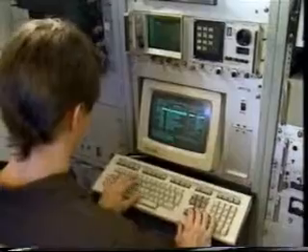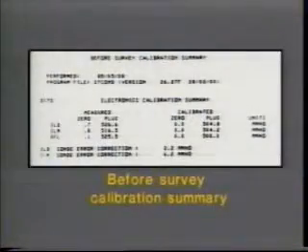Since this procedure is somewhat cumbersome at the well site, calibration resistors in the tool reproduce the values obtained during this periodic check. As with all logs, calibrations are performed before and after the survey and added along with the master calibration results to the log.